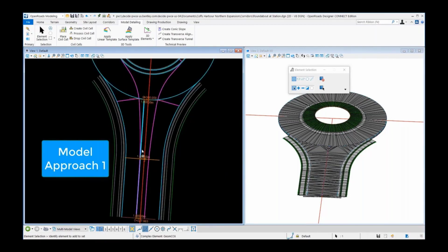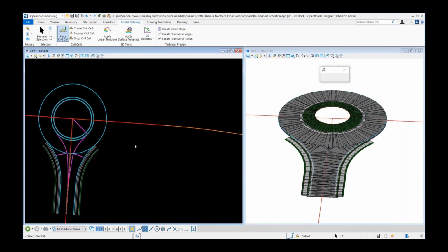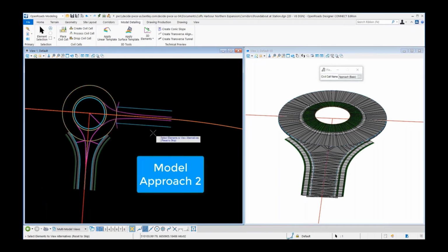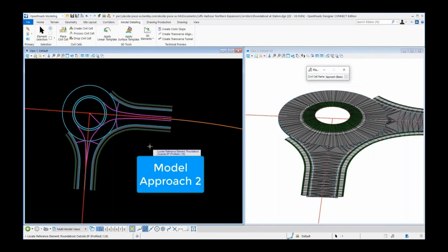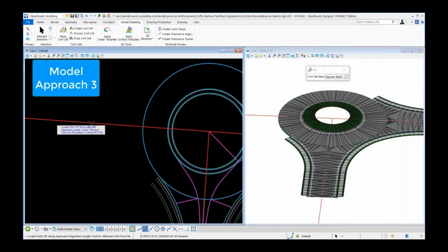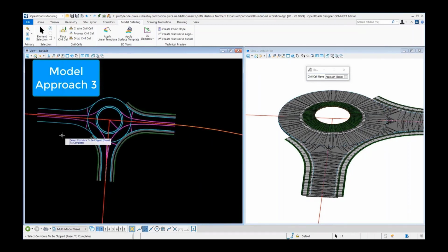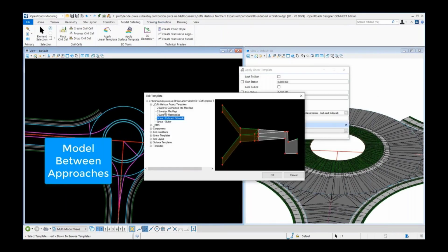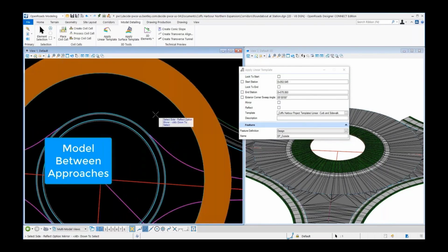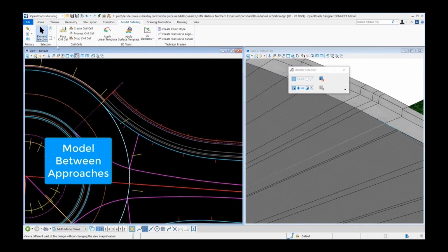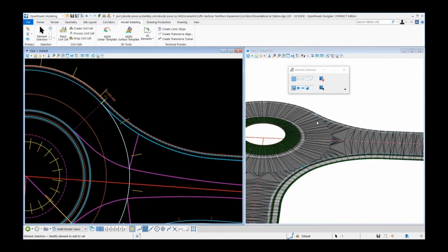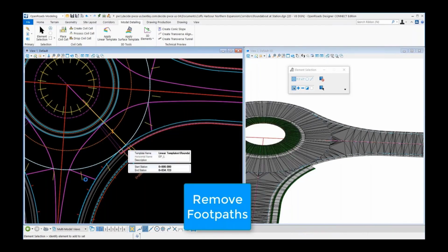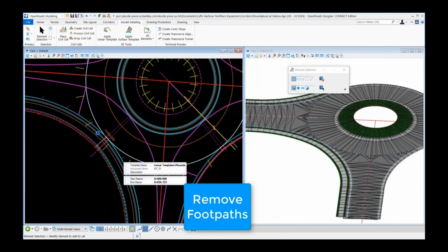So if you notice how fast it is to model a roundabout like this, which if you're using other tools, maybe you're doing it by using a wizard, right? That can sometimes be a bit challenging, or not flexible enough for you to adjust your design according to real life design scenarios. So again, the technology, if you notice, is still relying on templates saved in your DGN library. The DGN library is inside your workspace, and that enables you to design bigger or larger transportation facilities, as you can see here in this example.